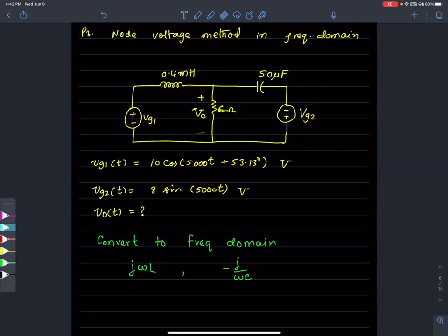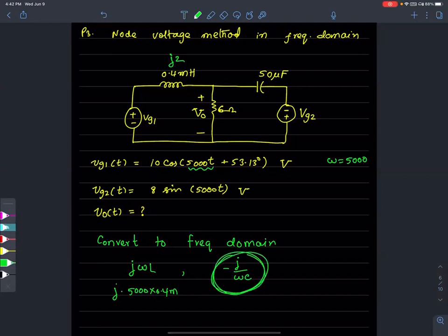What's the omega here? Omega is 5,000. If you convert this to 5,000, anybody can give me the numbers here really quickly? J omega is J times 5,000 times 0.4 milli, 2J. Thank you. How about this guy? Negative 4J. Thank you. So first things first, we converted this to frequency domain.